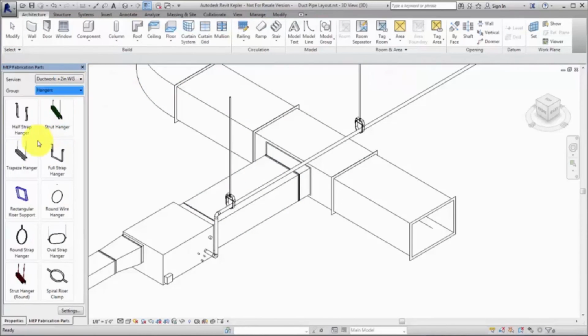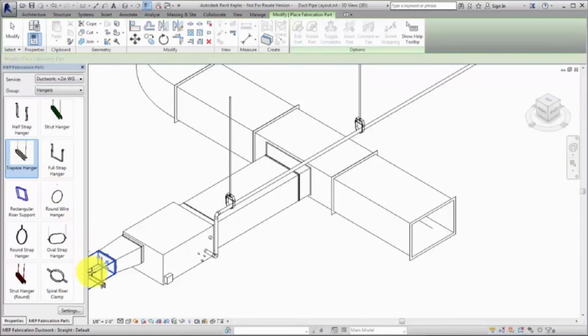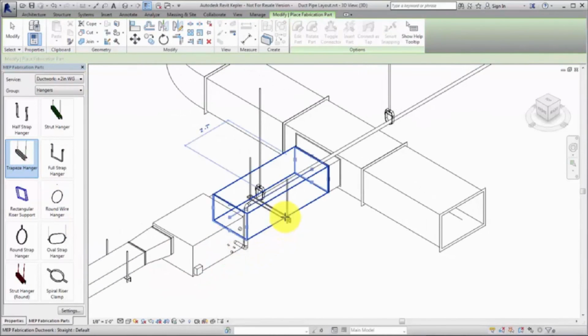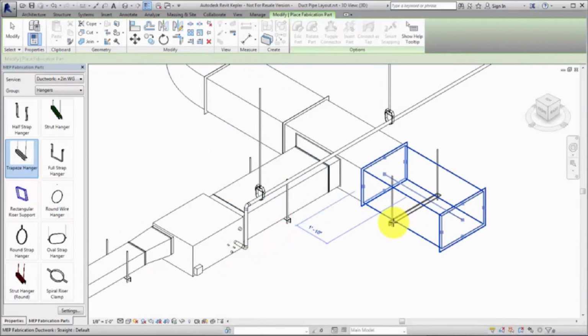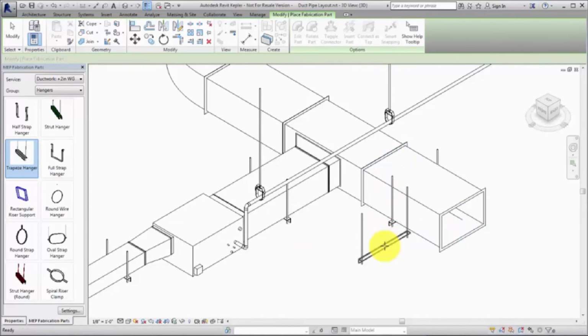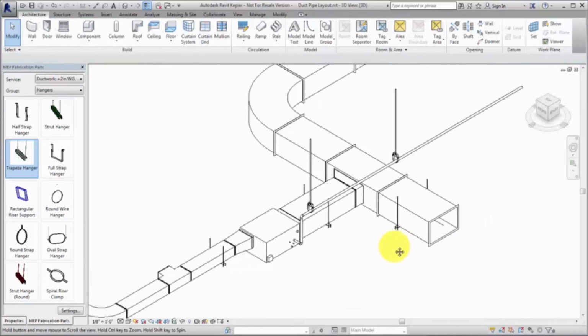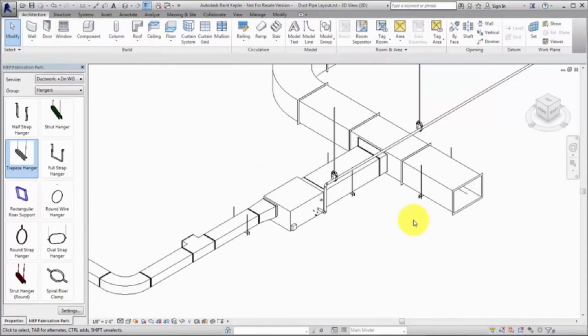By default, hangers are attached to the closest structure element. Structure categories include floor, roof, structure framing such as beam or truss, stairs, and slabs. If no structure element is available, Revit uses the default rod length as set in the ITM file definition.